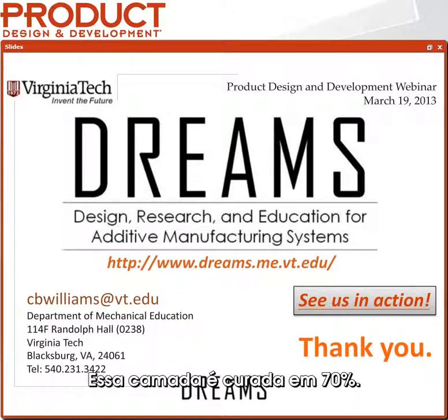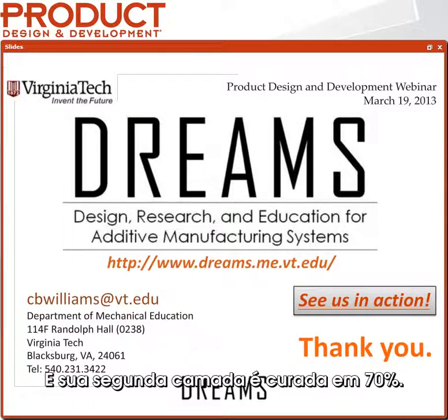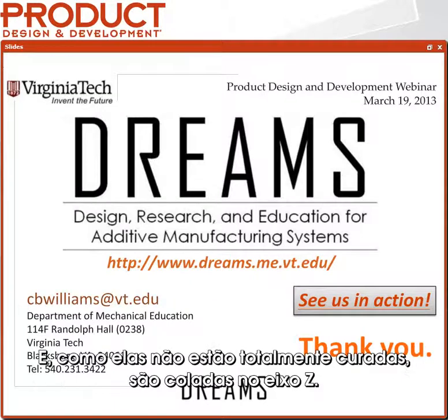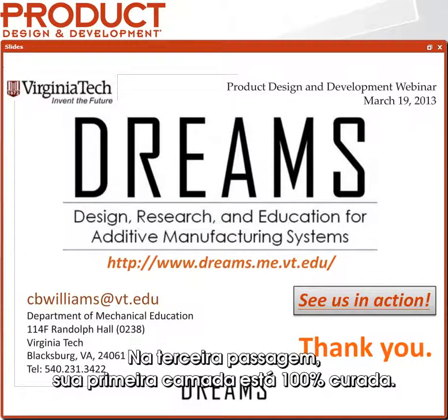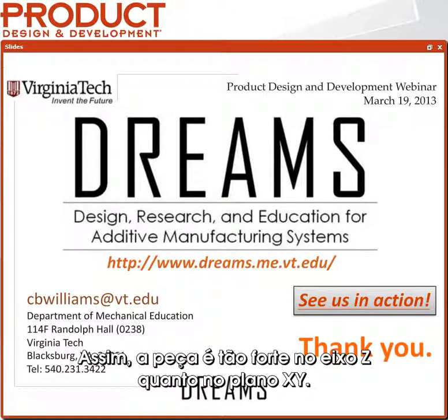And that layer is cured to 70%. The next layer that comes through, your first layer is now cured to 90%, your second layer is cured to 70%. And because they're not fully cured, they bond together in the z-axis. On the third pass, your first layer is now cured to 100%, your second layer is cured to 90%, your third layer is cured to 70%. So it's as strong in the XY axis as it is in the Z axis.